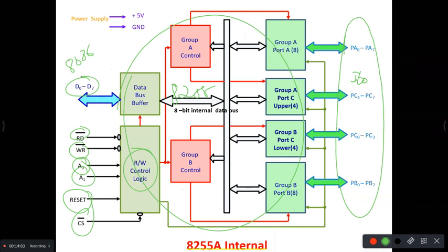Have you understood this? Okay? That's where you get your data from the microprocessor. The microprocessor will send the data through the 8255, through some port, to the IO devices. Suppose the microprocessor wants to get the data, it will come through one of the ports here, and then it will be received by the microprocessor. All of you understood this. That's what you have done in your last 4 experiments.